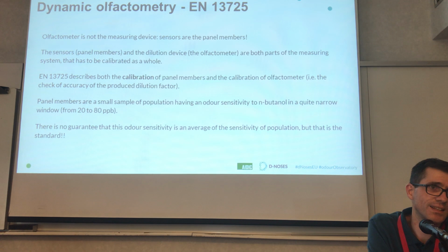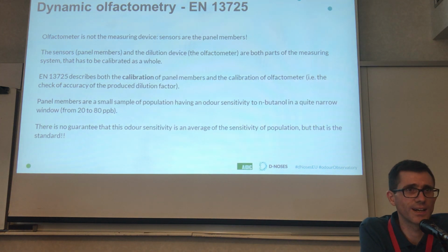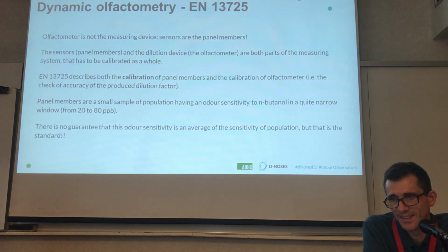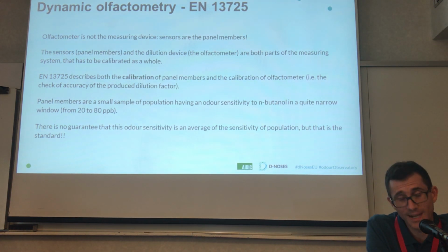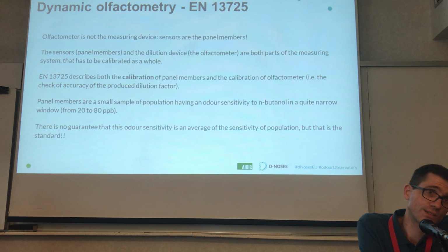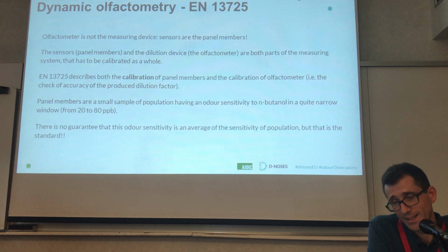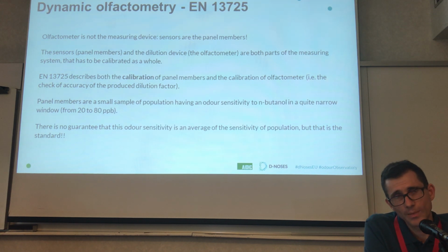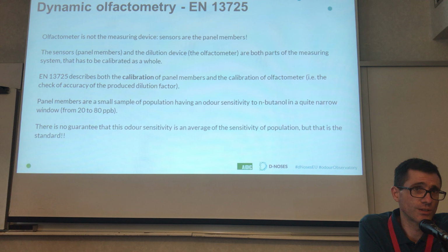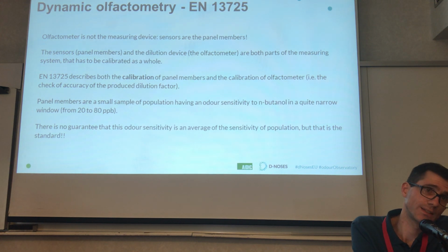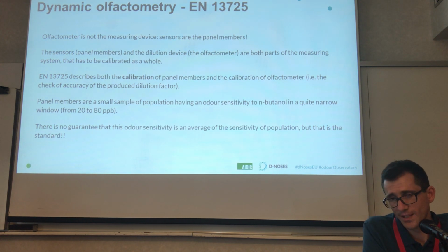The measuring device, the sensors, are and remain the panel members. But the standard provides both the requirements for the sensors and for the olfactometer, and contains requirements about the calibration of both the olfactometer and the panel member.